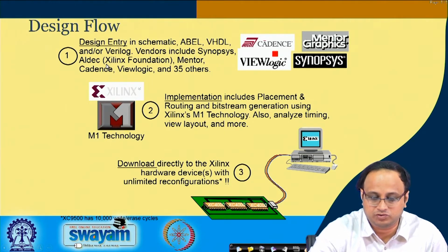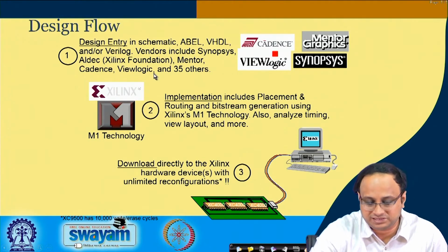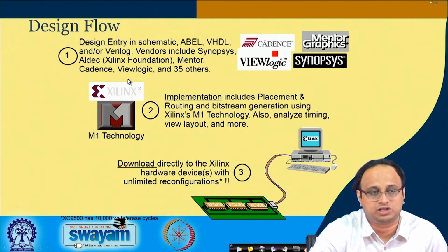So the design flow, you will see, starts with what is called an RTL description. You have got a design and you start with a basic RTL. You can implement your RTL using, say, Verilog or VHDL or some other languages, but typically Verilog is a very standard language which is adopted. Then you pass that to several CAD tools. Again, you have got several CAD tools, like Xilinx and